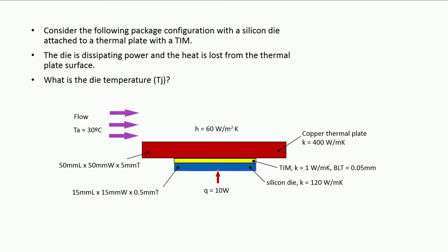Now, one thing I want to tell you over here, and we will again discuss it later, is, as Professor Dasgupta was saying, even surfaces that appear very flat, absolutely polished, have a lot of surface roughness if you go into the micro scale. Now, when you put these two surfaces together, what happens? There will be air voids, cannot be a perfect contact. We cannot eliminate that, but air is one of the worst thermal conductors, as you see. It is going to give rise to a lot of thermal resistance. It is a resistance to the heat flow path, it is going to block heat flow.